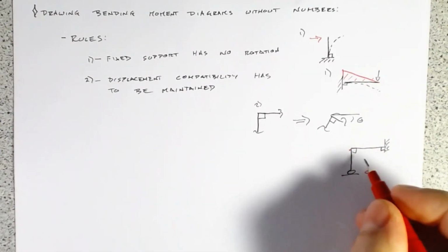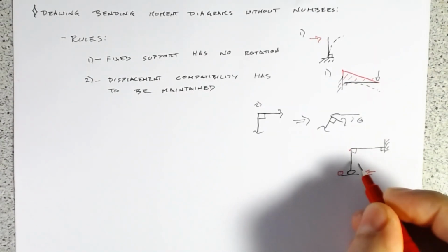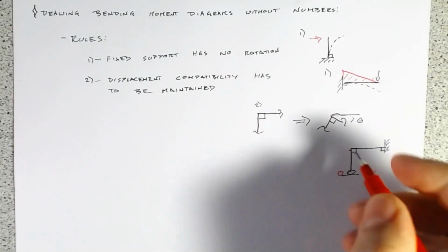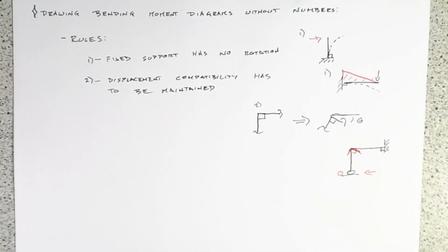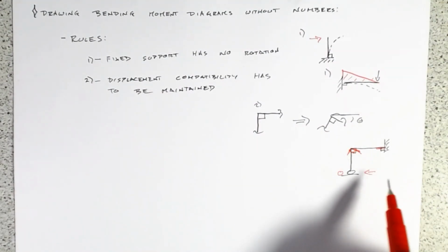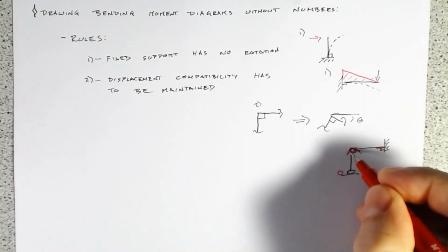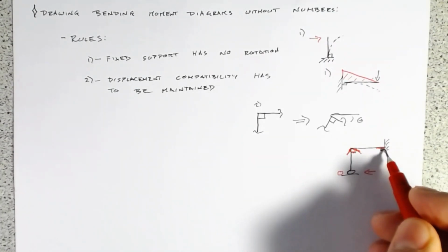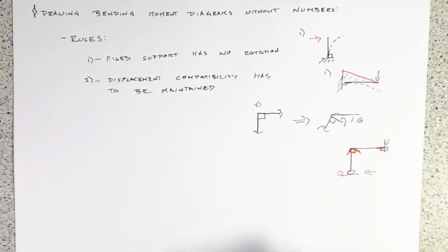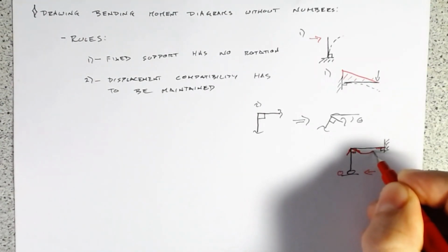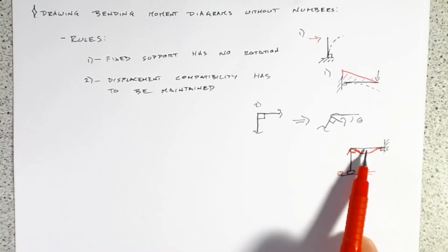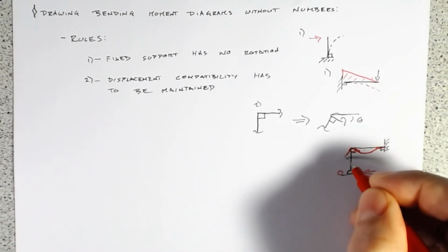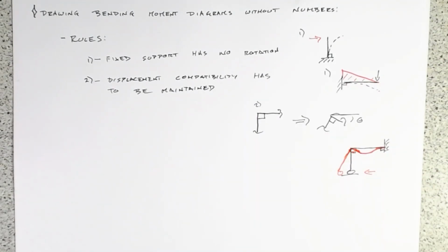Just help the light there a little bit. Well, we know the support's going to go there. We know that that's going to rotate this around. So we'll draw that. We know that this has to stay at 0 coming out. So if our corner is sort of fixed in its orientation here, and the fixed support's there, then the only way we can accommodate these rotations is for this beam here in the middle to bend. And so that's kind of what our deflected shape looks like.